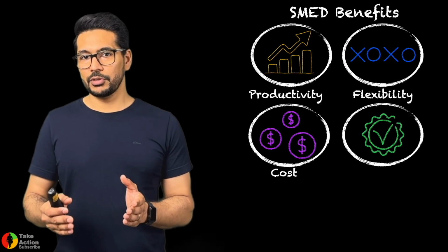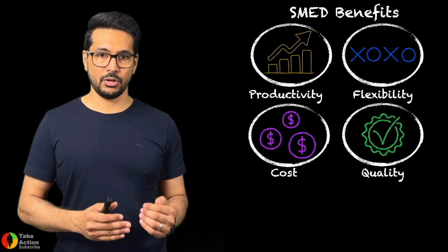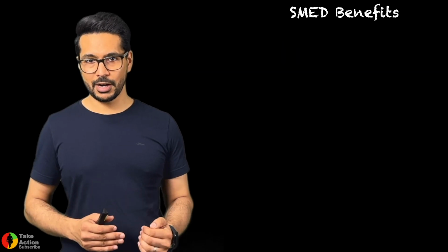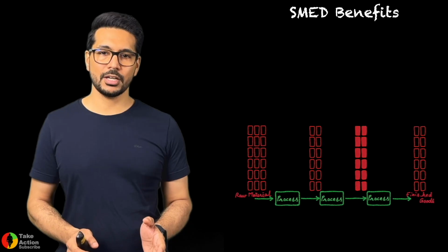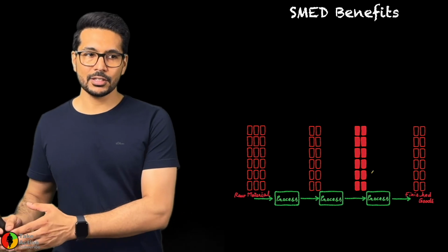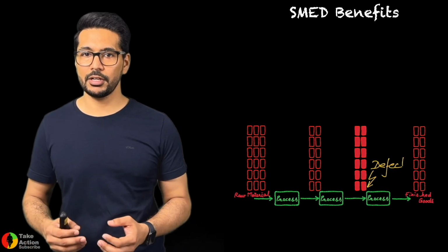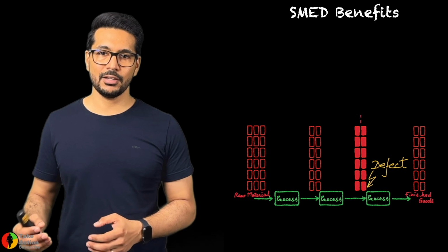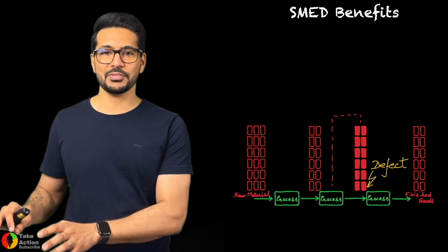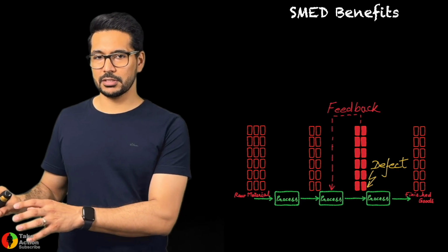We have seen that if we reduce the setup time, we can reduce the lot size. So imagine again we were producing 100 parts and sending this lot of 100 parts to our customer process, and there it could detect a non-conformity, a quality defect or anything. With that, the probability is very high that all the 100 parts are affected by this defect.